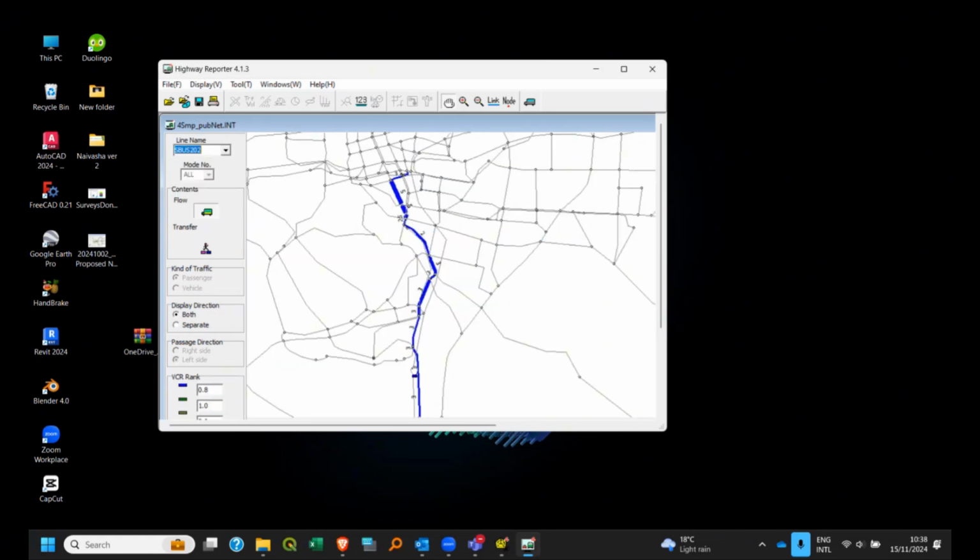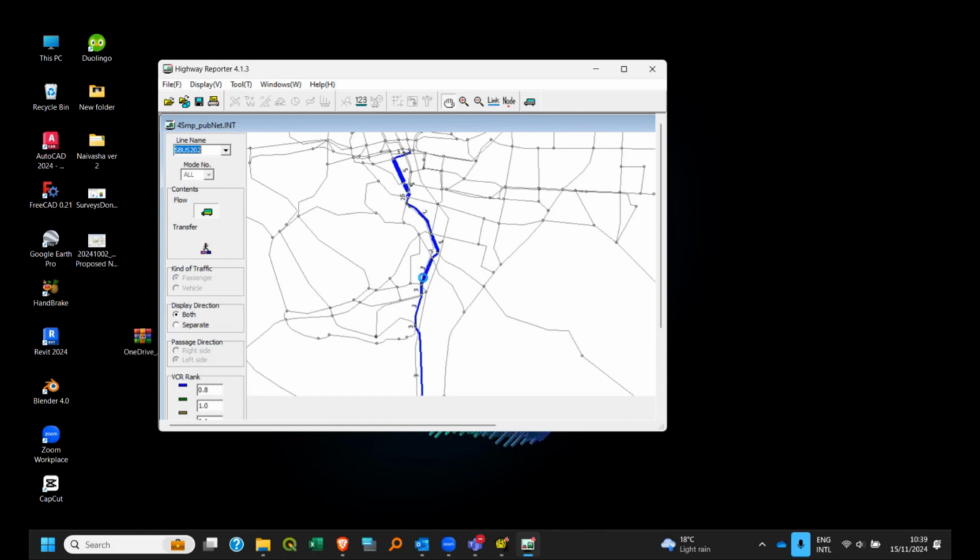Then if you would like to calibrate more specifically, you need to collect the actual statistical record of the public transport ridership by the route. So you can compare with the actual passenger volumes of each transit network result.